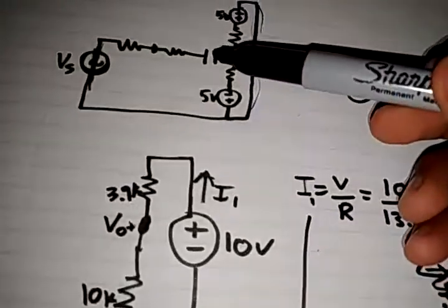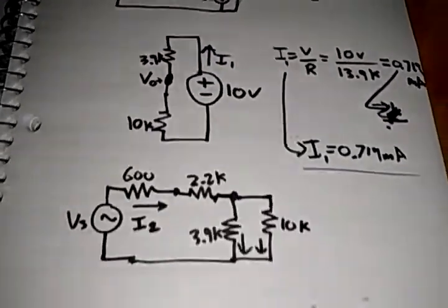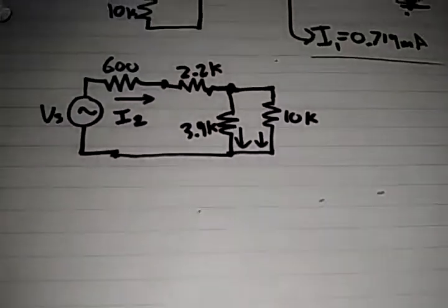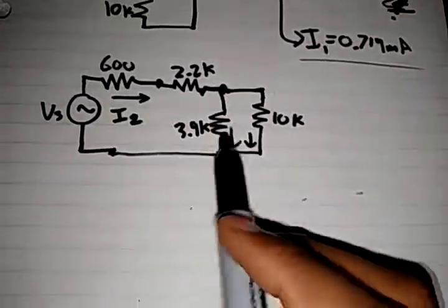Notice that the question states that we can assume that the capacitor will be a short circuit for the AC current, because the AC is meant to be 20 kHz. So if we have this, then we can simply find I2 by finding the R equivalent.